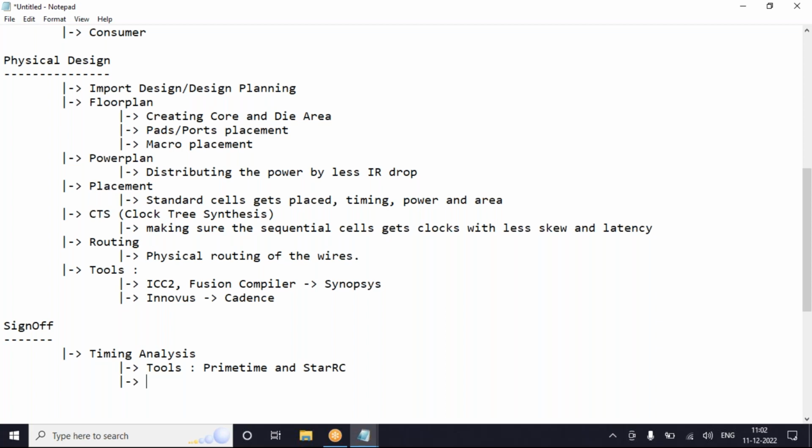Here, PrimeTime is a logical entity tool which you will be using at different stages. After synthesis, after placement, after CTS, after routing, you can use this particular tool. It's a logical tool. Based on the input, this tool can also be helpful for physical related operations as well. Synthesis and PrimeTime are logical entities where you cannot see your design. Okay, you cannot see your design, you can see only the schematic. What is the difference between schematic layout and schematic?